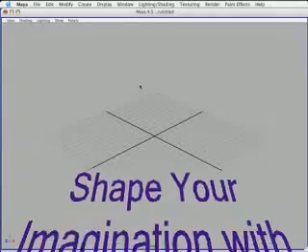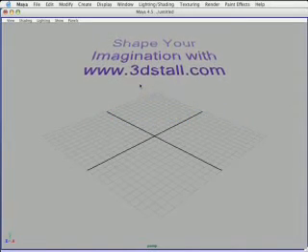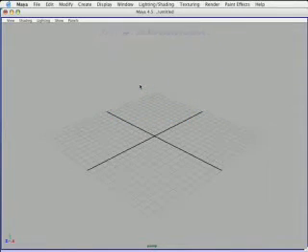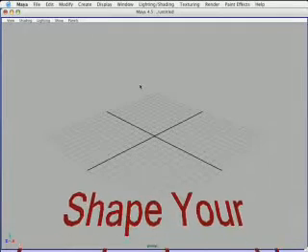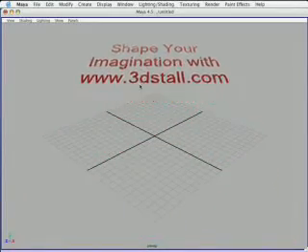Sometimes it can be faster to model objects that are relatively flat using textures than to actually model them with geometry. This technique goes by various names such as stencil mapping, stencil masks, making cutouts, putting images on cards, and using image planes. They all consist of putting an image on a flat or partially curved NURBS or polygon plane. In architectural renderings, pictures of people, cars, and trees are put on planes to save time.